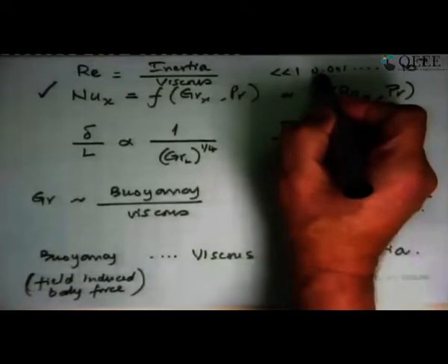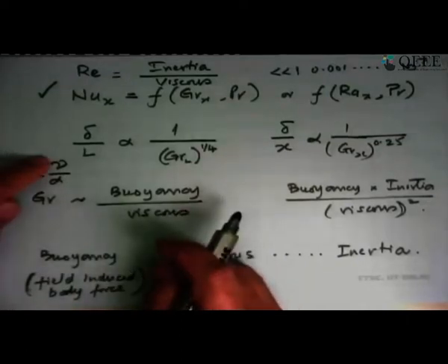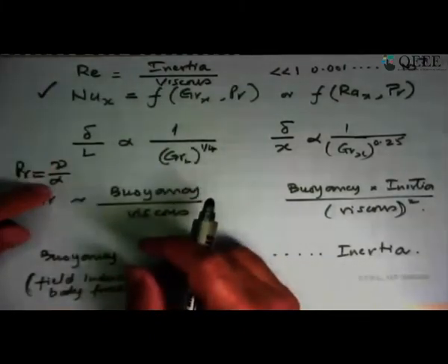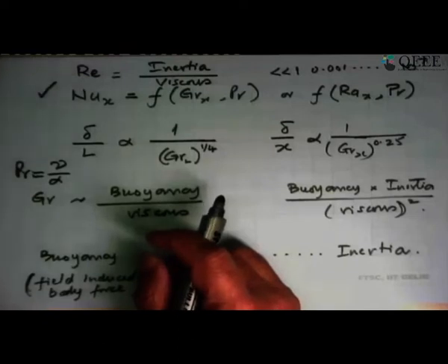Here, viscous forces completely dominate the flow. Here, viscous forces are very, very weak. They are not all that important, but they do come into play here. Okay, so that was Reynolds number, inertia to viscous forces. Then we came across Prandtl number, which was mu upon alpha: momentum diffusivity in a fluid, the rate at which the effect of, say, velocity gradients is felt, divided by thermal diffusivity, the rate at which energy can go through it and the effects of temperature gradients are felt. So those are the two non-dimensional numbers we have come across so far.